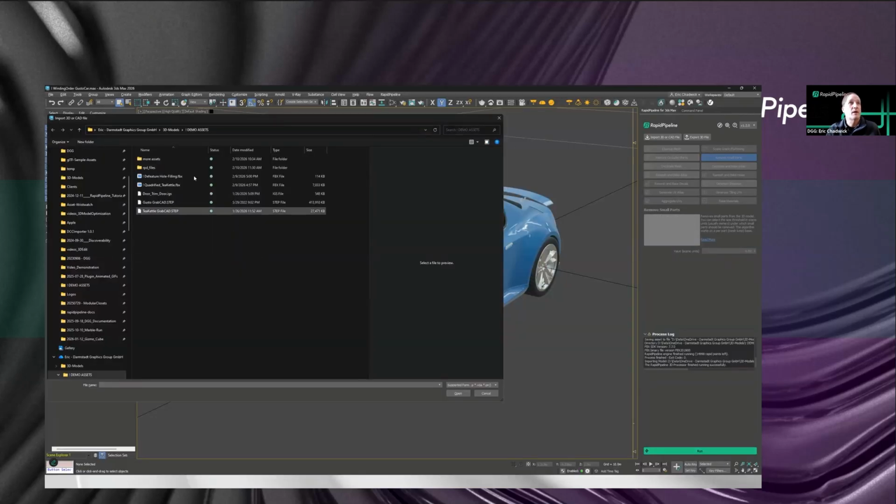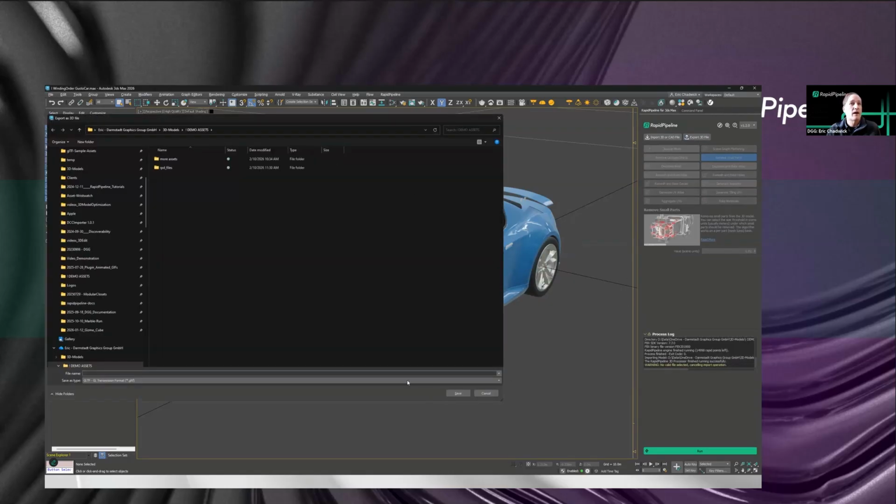And basically, we support importing all of those formats, right? But for export, we have a more fine-grained set of files that we can export. We can't go directly back out to a CAD format, for example, because it really doesn't make sense. That's a parametric surface, and we're working on triangulated meshes, things that are ready for rendering and for web real-time export. And so it makes sense to support those formats. We have USDZ for going out to Apple devices. Usually GLTF is the great one for web and for PC devices or Windows devices, and then a bunch of other formats that make sense for various things.